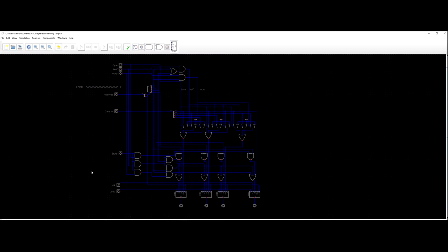Like in the real world, I'm building a test board for a bunch of fiber optic. There are 3 test boards that the customer has. Their data capture board, which pulls data from their computer. The data capture board then sends the data via low voltage differential signal to a fiber optic transmitter board. That transmitter board then has 29 parallel fiber optic cables that go to a fiber optic receiver board, and that receiver board then brings that data back in through a single-ended cable.